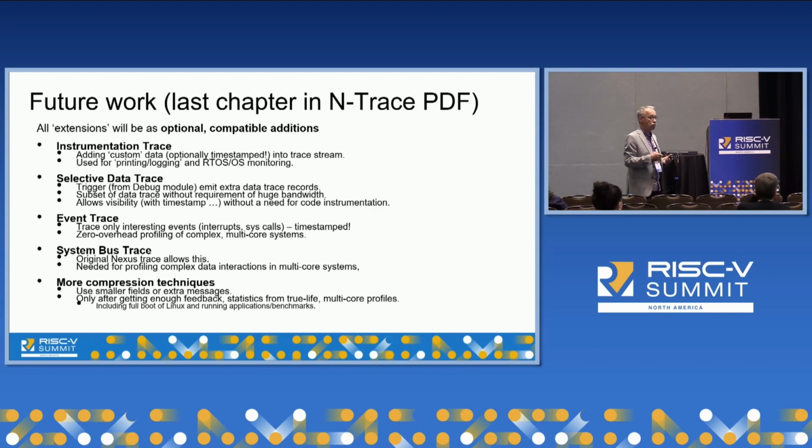Instrumentation trace. Sometimes you want to instrument code a little bit to give a focus and maybe some data, and also timing information. If somebody was at the E-trace, event trace, that's a similar thing, some extra data with extra timing, extra information, right? So that's what I call selective data trace. Compared to ITM from ARM, you may send some data out of your application to a trace buffer. Just use it as a sort of UART kind of style.